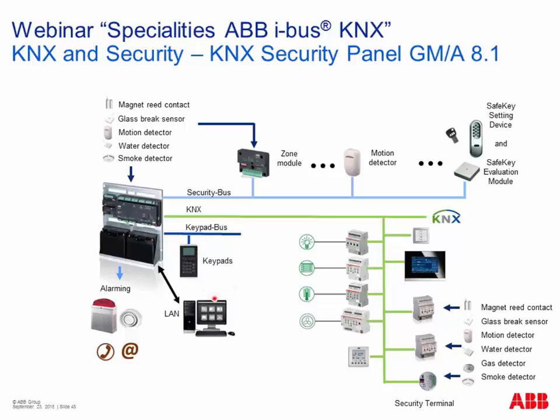The complete commissioning of the system, for example the programming of all our modules like our zone modules, motion detectors or arming devices, we do via IP. So we need only a standard browser, which can be a laptop or, for example, a tablet. It's also possible. So this is the professional solution.